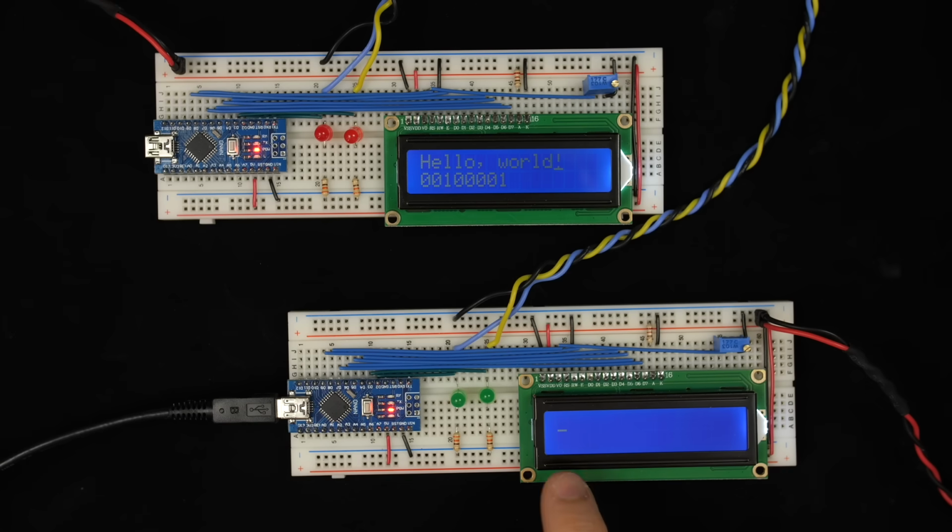The first thing you'll notice is that we're not receiving those zeros anymore. Remember before, every 200 milliseconds, it would look at the data signal, and if it was low, it would say, well, must be receiving a zero, and it would just receive a zero every 200 milliseconds. But now it's actually waiting for that clock, so we don't see it just printing those zeros like it was before. The other nice thing about that is that it's not only waiting for the clock to receive a bit, it's waiting for the clock to receive the first bit.